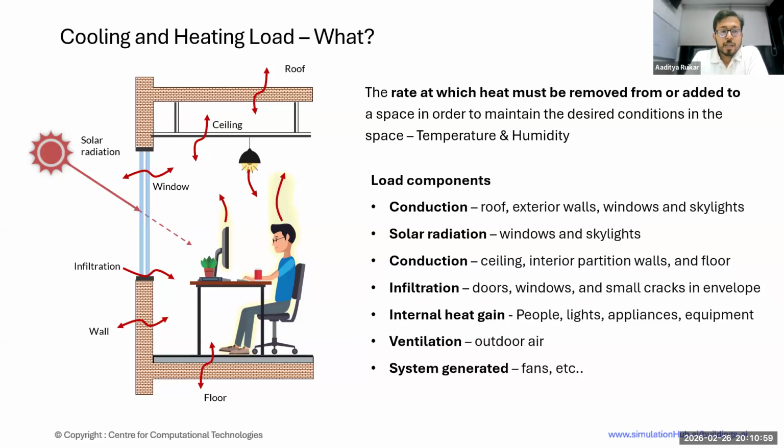So it starts from the solar load. Solar load is the major contributor for buildings, as it comes through windows, fenestration, and opaque surfaces. Then the temperature outside the building also drives temperature-driven heat gains or heat losses based on your location.